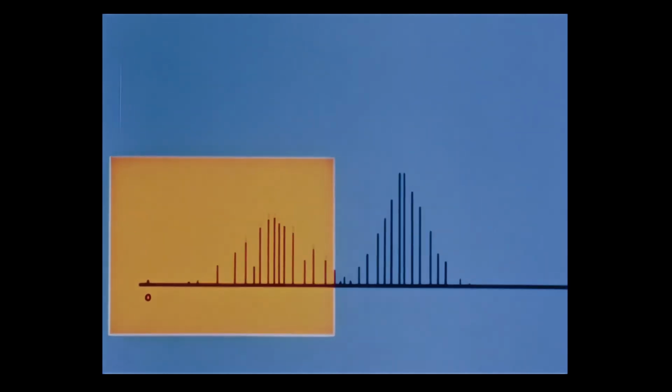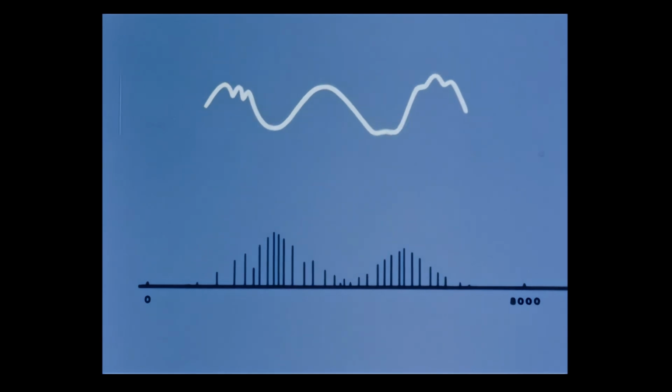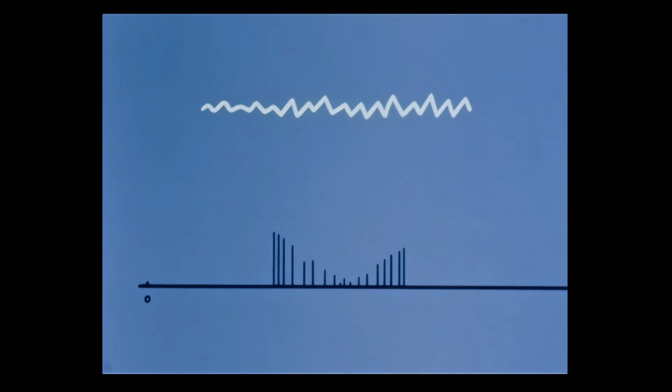The human voice, which can be likened to a musical instrument, is best depicted on the larger spectrum. On an average, the frequency range is about 8,000 cycles. The associated wave shape looks like this. By filtering out inessential harmonics, we can reduce this range to 3,000 cycles.